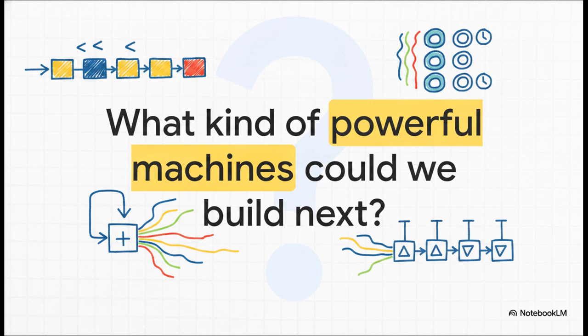We've just seen how non-blocking syntax acts as the absolute perfect wire for building shift registers to move data sequentially. But I want to leave you with a thought. If this simple, concurrent, less than or equal to sign strings memory together so effortlessly, what kind of absolute powerhouse counting machines could we build next by simply introducing an adder into this feedback loop? Well, I'll tell you, that is the exact gateway to building synchronous counters, opening up a whole new world of complex hardware design for us to explore.